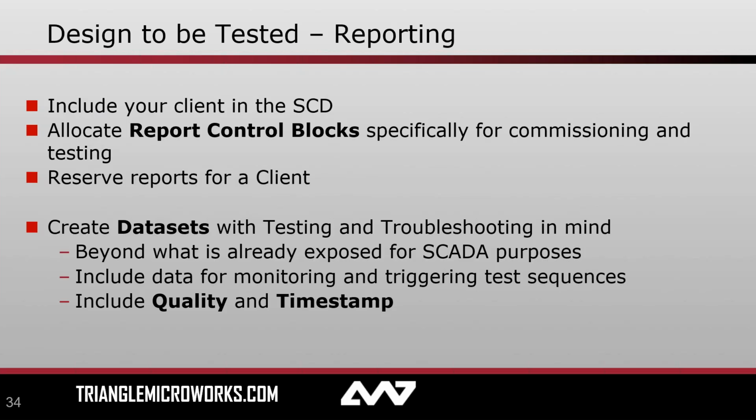That might go so far as to actually reserve specific control blocks for that client, meaning that other clients out there, like maybe your HMI or your gateway, will not be able to grab those report control blocks and use them for themselves. You don't want to get into a situation where you're trying to test, you need some data that's maybe not available via Goose but is available via a report, and those reports aren't available because they're already all being used up by other clients.